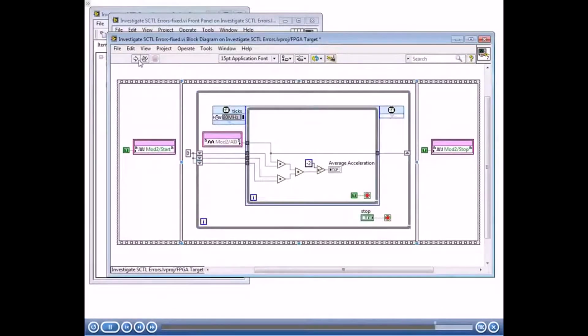And if I were to run this, I'll just let you know right now that at 80 megahertz, that code will be able to compile. We saw that there was a total delay, I think, of about 9 nanoseconds. So if you do 1 divided by 9 nanoseconds to figure out what your maximum frequency is that it will compile at, 80 megahertz is well below that. So this should compile. So I'm not going to take the time to compile it here, and you can just take my word for it, or you can do the exercise.